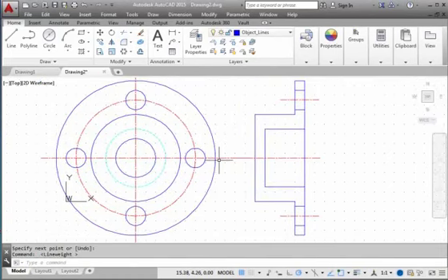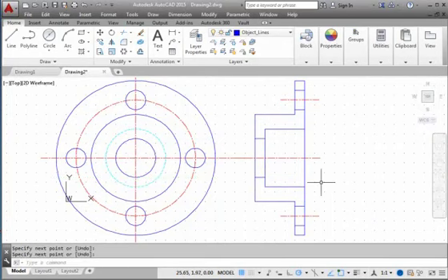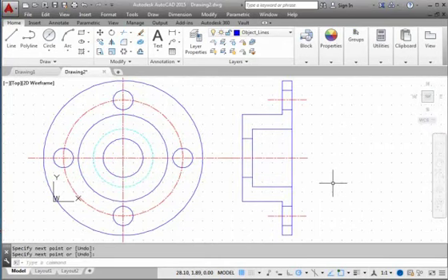Now the side view is going to be a section view. In the front view, we are cutting through the center of the design. So the side view is showing only half of the design and cutting marks are right through the center. In the side view, we only need to indicate the small hole on top, the large hole at the center, and the small hole at the bottom.